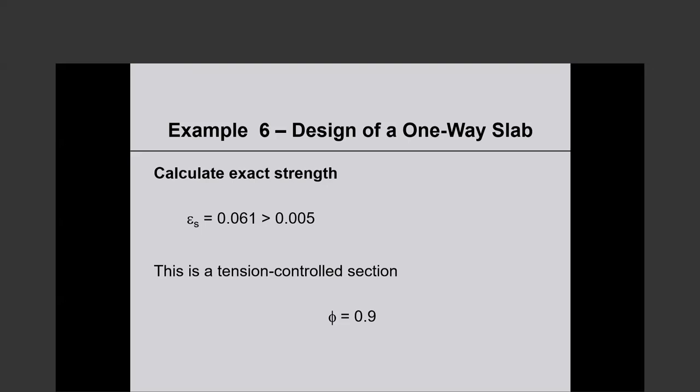If required compression steel in a beam is found high, and if a, that small a, is less than slab thickness, can we distribute rebars in part of adjacent slab to avoid congestion?